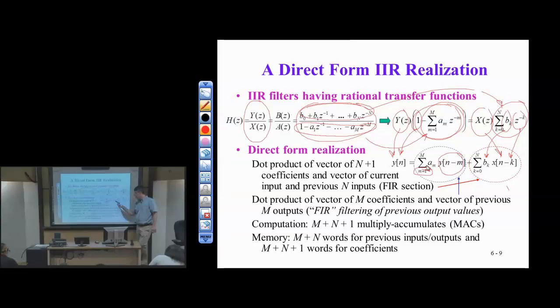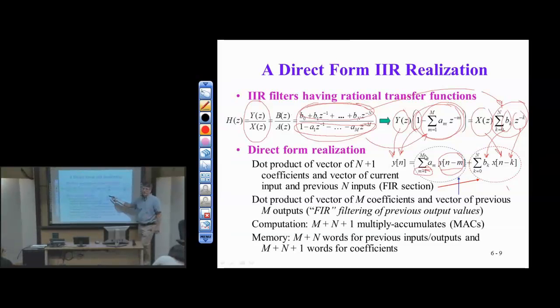Okay, so again, back to this term, this left term here. This is a tap delay line, and I'm just storing the previous output, the output 2 samples ago, all the way up to the output capital M samples ago. It's just a tap delay line applied to the previous output samples and nothing more. And so I pick off the right delayed value and I scale by the appropriate feedback coefficient, a sub m. In C code, it's just 2 for loops. Multiply, add, multiply, add, multiply, add.